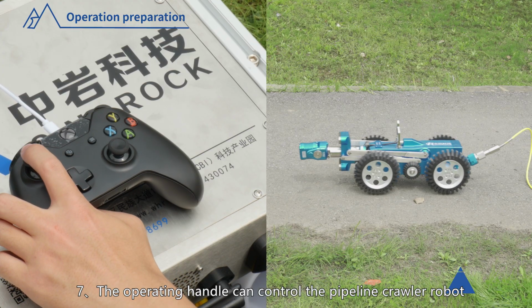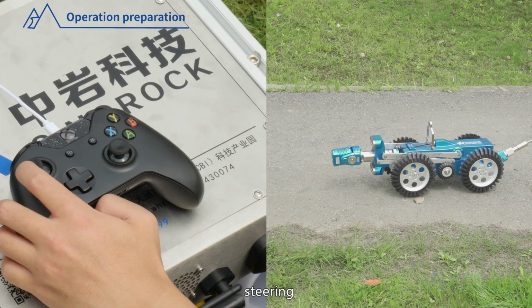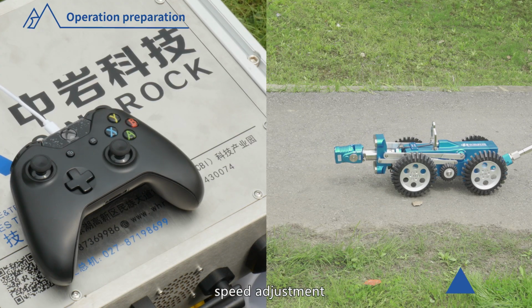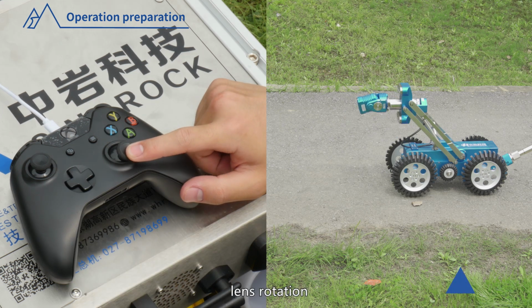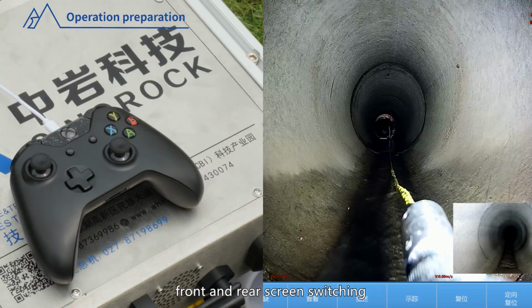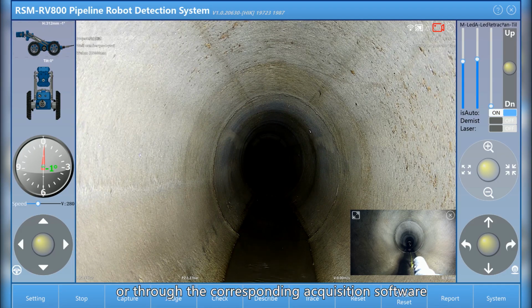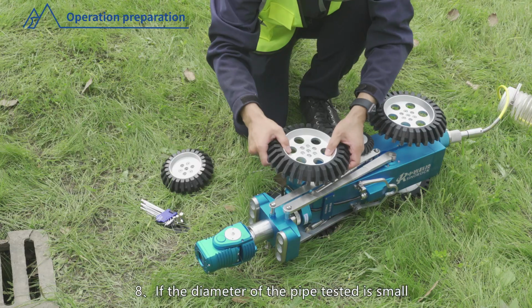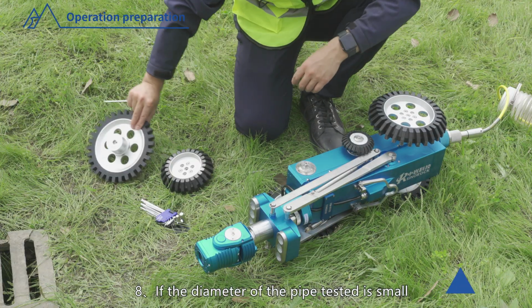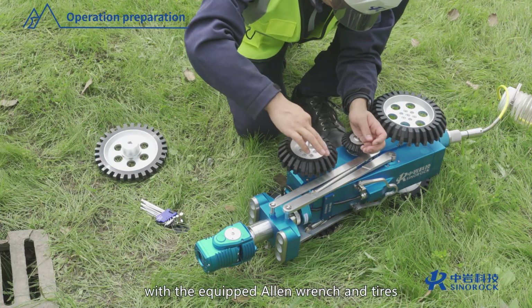7. The operating handle can control the pipeline crawler robot to go forward, backward, steering, speed adjustment, pan tilt lift, lens rotation, lens one key reset, front and rear screen switching, as well as light brightness adjustment and other functions, or through the corresponding acquisition software control buttons for control. 8. If the diameter of the pipe tested is small, it can be directly replaced on site with the equipped Allen wrench and tires.